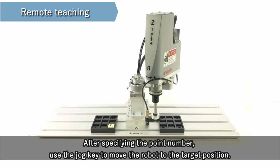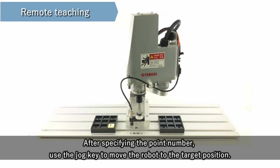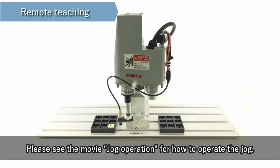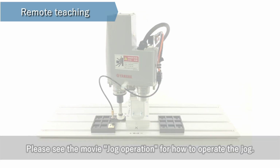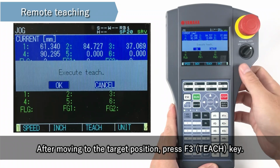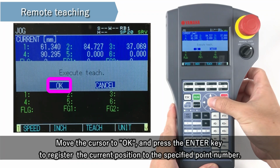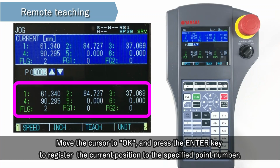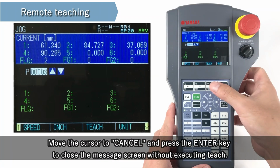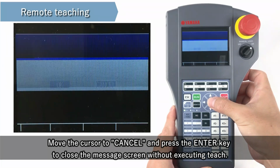After specifying the point number, use the jog key to move the robot to the target position. Please see the movie jog operation for how to operate the jog. After moving to the target position, press F3 key. A confirmation message Execute Teach is displayed. Move the cursor to OK, and press the Enter key to register the current position to the specified point number. Move the cursor to cancel and press the Enter key to close the message screen without executing Teach.